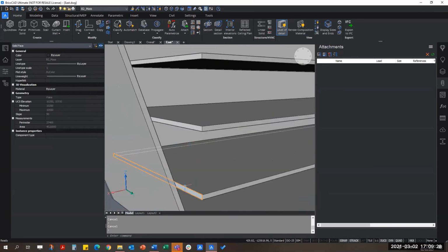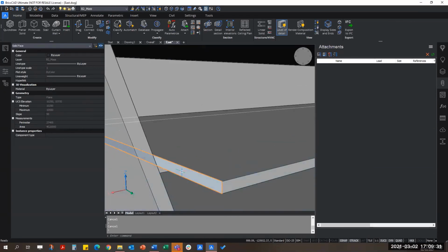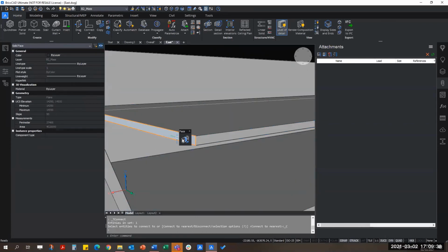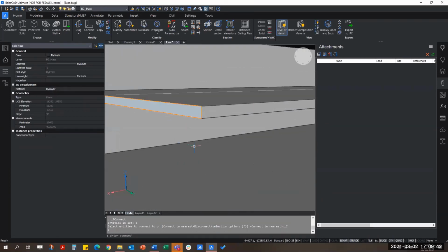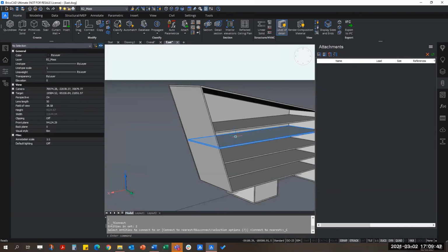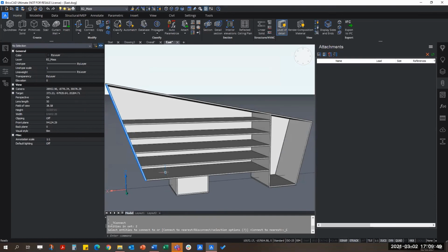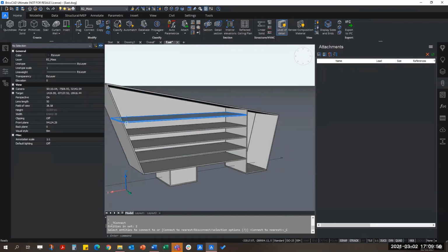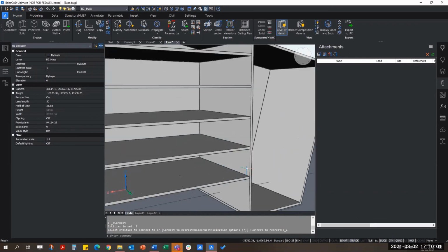And once I'm happy with it, again, I'm going to do this, connect to nearest. And because I've used that one now, the next one on my quad, you can see the AI tools kicking in again. Now I think you can even double select it. There you go. You can select multiple faces, shoot it this way, and here you go. My floor slabs are touching this side of my external wall and internal wall.